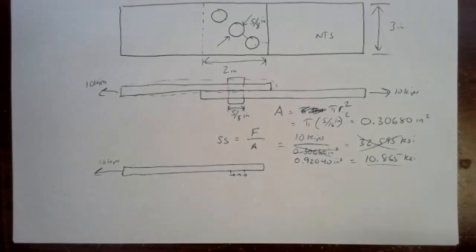Any questions there? If you put multiple rivets, that would multiply the area, not add them up. It adds the area. It multiplies it by the number of rivets you've got. Otherwise we'd end up with inches to the eighth and things like that. You'd add the area. So rather than having one big rivet with that area, you can split it up into 3 smaller rivets with a third of the area each. As long as the area in total is correct, the area you're spreading that force out over,